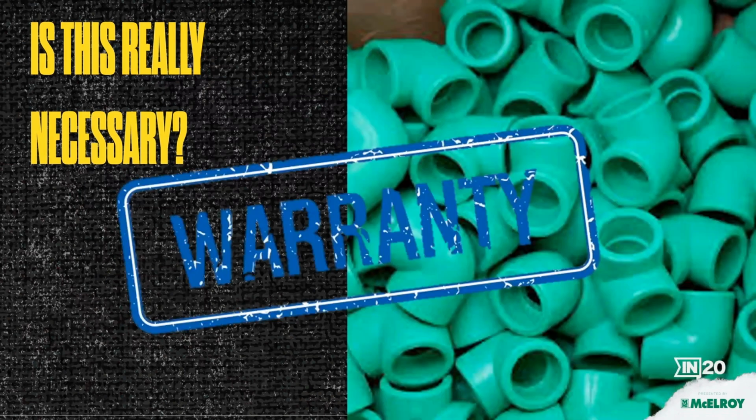What about warranty? And this may apply more to those of you in the PPR side of the industry, because all the major PPR or PPR-CT manufacturers offer a significant warranty on their products. And those warranties will not be provided unless a documented pressure test that is performed per their procedure has been submitted. And in some cases, fusion records, inspection records, those may be required as well. There are potentially millions of dollars hanging in the balance, and the direction that those dollars fall could very well depend on a properly performed pressure test. So again, that pressure test carries a lot of weight.